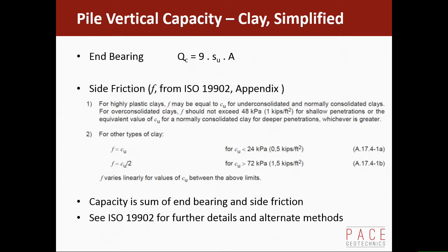That's one of the times where the volume of soil in the pile becomes an issue, because some people, particularly for mooring piles, in theory can drive them below the seabed, and your mooring chain is often on a pad 5 or 6 metres below the seabed, and the top of the pile doesn't actually do much. So in theory you only do that, but then you find the follower, which is usually plugged into the pile, gets full of soil around it, and then you can't get the follower out. So you end up with a bit of a problem, really.